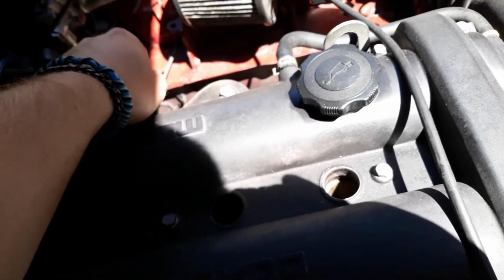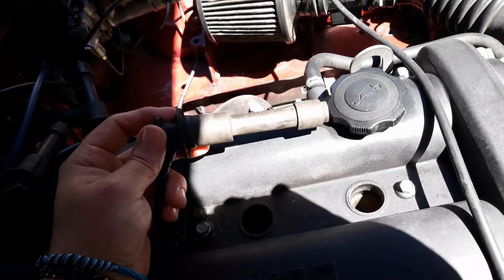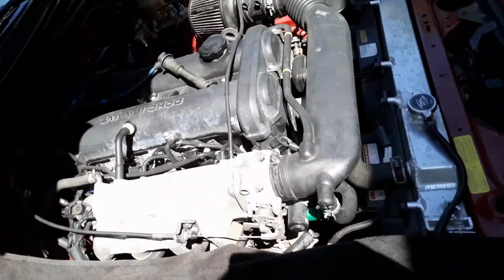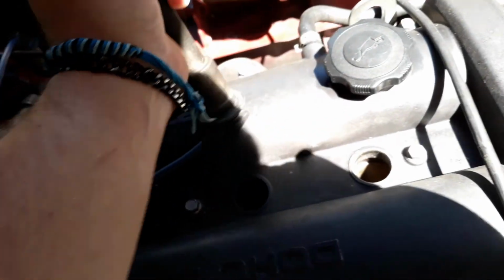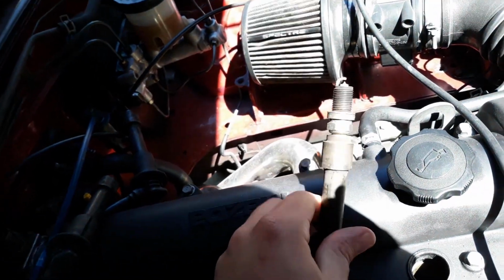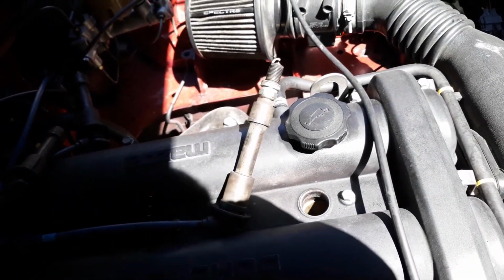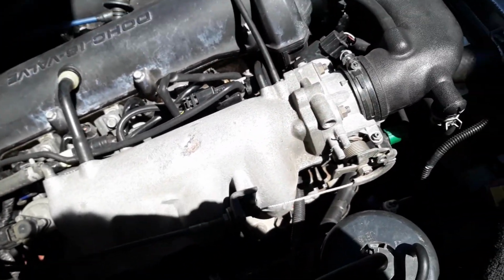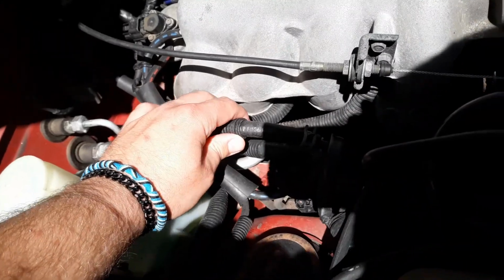So you see I've got spark. This one has spark plug wires and spark plugs. If you want to prove that it has spark, it's as easy as pull the coil off or pull the spark plug wire off. Go grab your spark plug. And of course this one is broken, but the point is, all you have to do is stick it back in either the coil or the spark plug wire. Now don't hold it by hand because it might shock you, but go get something insulated or put it like this and have your friend turn the engine over. And when you watch it, it should be a bright blue. You should be able to see it like lightning.